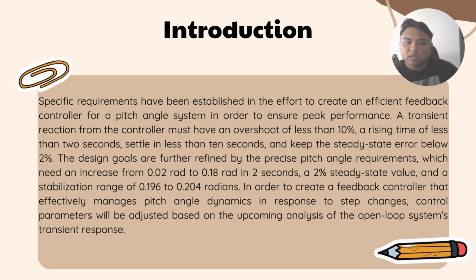The design goal is further refined by a practical pitch angle requirement, which needs to increase from 0.02 radian to 0.18 radian in 2 seconds, with a 2% steady-state value and a stabilization range of 0.196 to 0.204 radian, in order to create feedback control that effectively manages pitch angle dynamics in response to step change. Control parameters will be adjusted based on the upcoming analysis of the open loop system transient response.